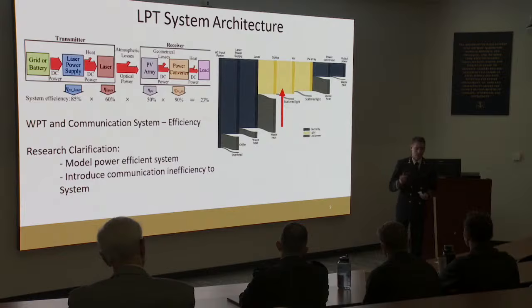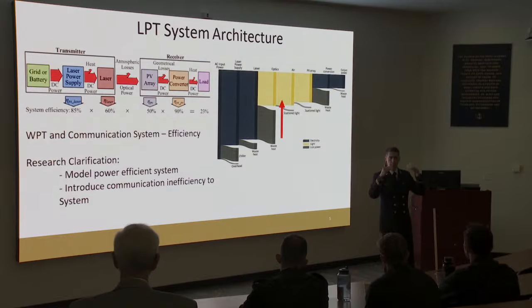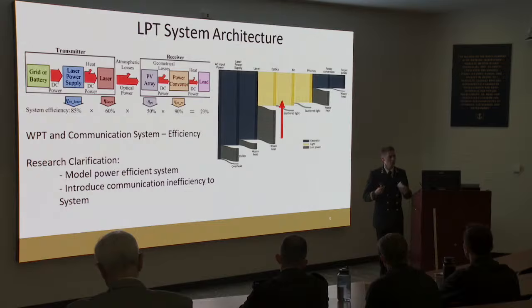So what does that mean? Essentially, you're modulating the laser diodes that you're transmitting the power with to different power levels. Each of those power levels is associated with a bit, essentially allowing us to establish a communication link with the solar cell that we're transmitting to.